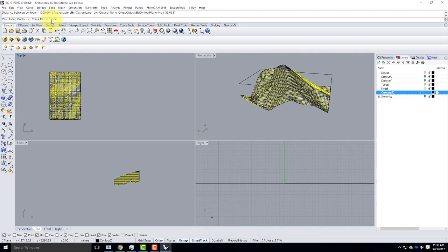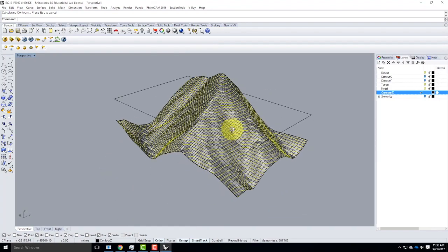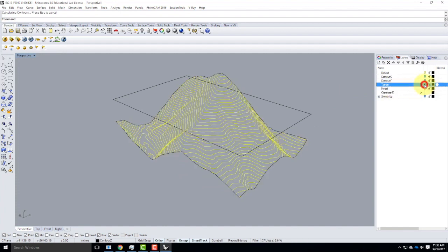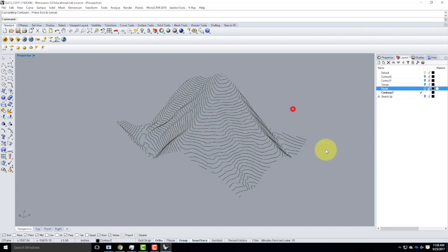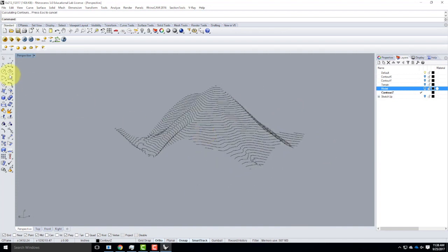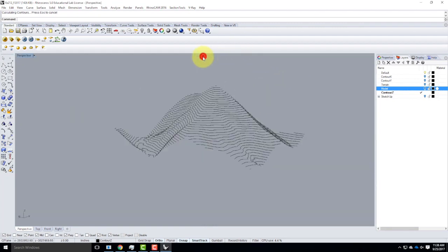into all the individual little contours that it'll take to make this model. So I can look at this now as a bunch of stacks, so to speak, of pieces of cardboard. So let me go ahead and turn off my terrain. And I could actually turn off my model, and I'm left with all of those little pieces. We can confirm that it was done correctly by looking at it in the side view, and they should all be perfectly horizontal lines. That's what we're looking for.